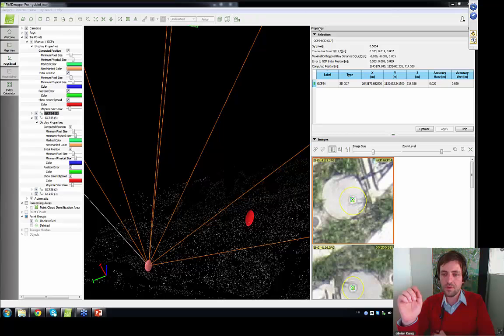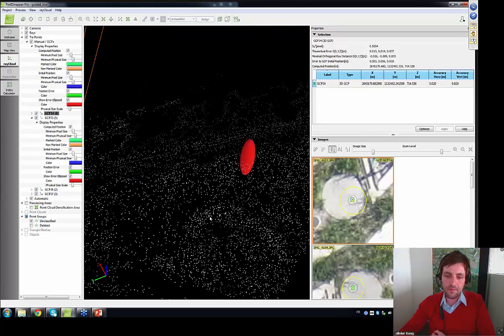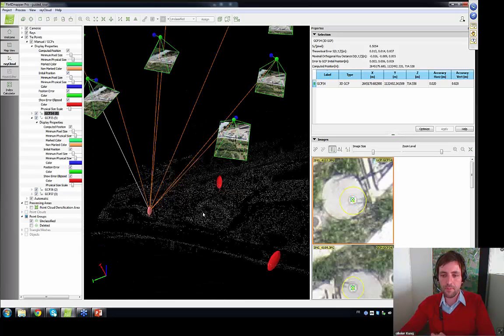So this is only when the project is already in a weird state, when you already have some issues in the project. There, what's usually the most time consuming is adding manual tie points. So probably adding a few manual tie points clicked on many images is going to be more useful for the software than a ton of manual tie points which are badly clicked. So it's the second one which I would recommend: clicking only a few manual tie points, making sure that they are well clicked.